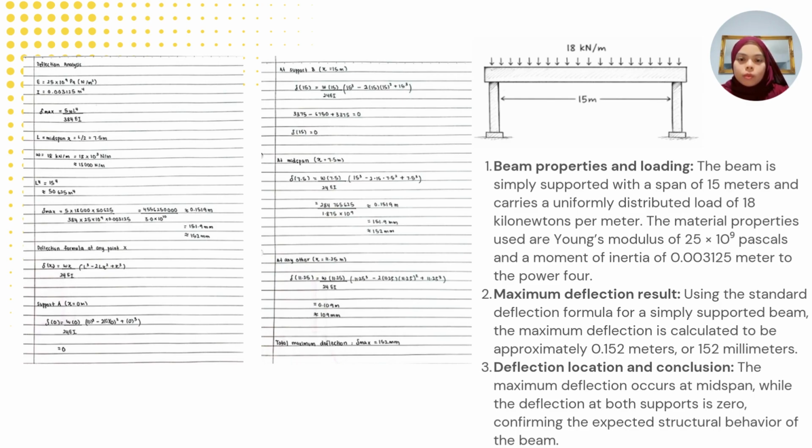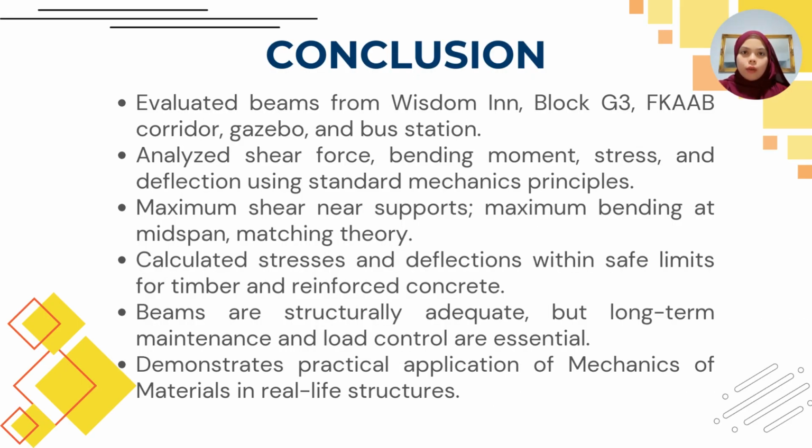In conclusion, this study evaluated the structural behavior of several beams from real-life structures, including Wisdom Inn, Block G3, the FCAP corridor, a gazebo near the Pusat Kesihatan University, and a bus station. Each beam was analysed using standard mechanics of materials principles to determine shear force, bending moment, stress, and deflection under applied loads. The results show that maximum shear force occurs near the support, while maximum bending moment occurs at the midspan, which agrees with theoretical behavior.